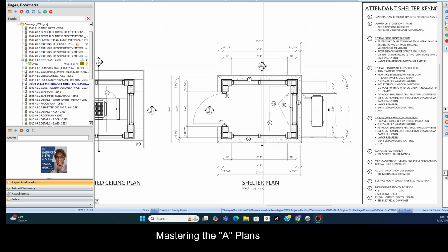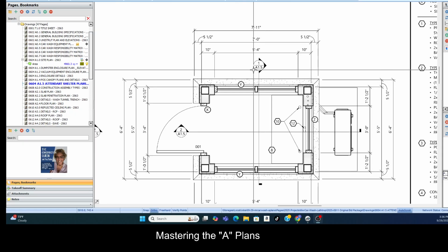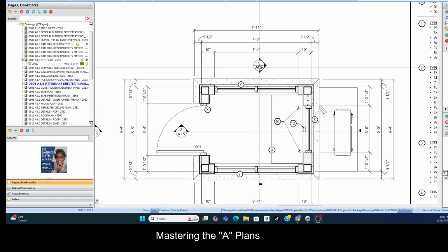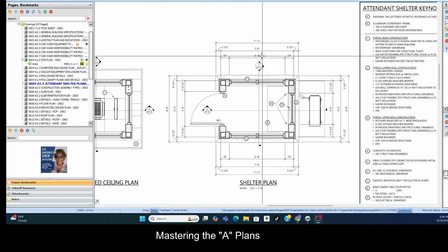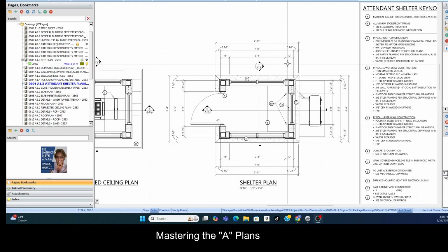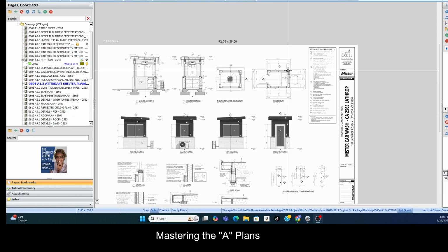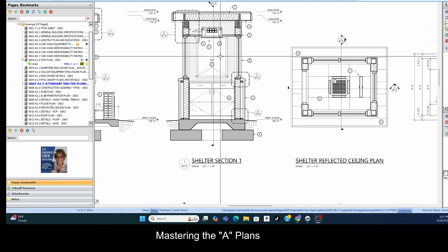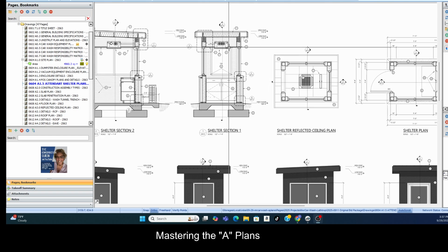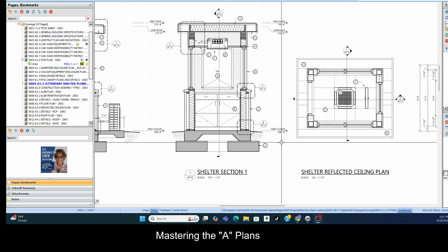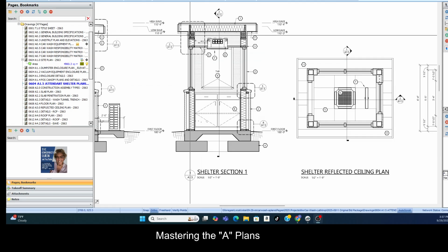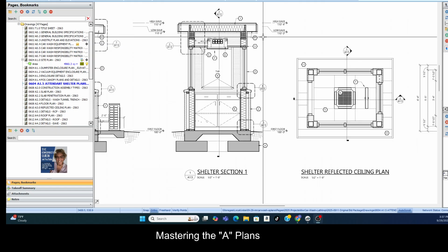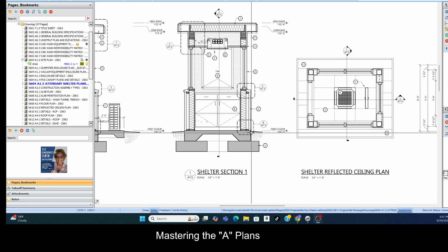And so again, the section view action is as if we took his leg and cut the building, like here's our loaf of bread. So we cut the building, and now we open it up and we're standing right where his leg is and we're looking in that direction. So 1 over A1.5, that is here. In terms of walls, now we can determine the height of the walls, and we're going to include that whole height, from the roof to the foundation.